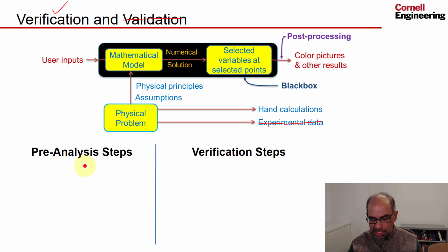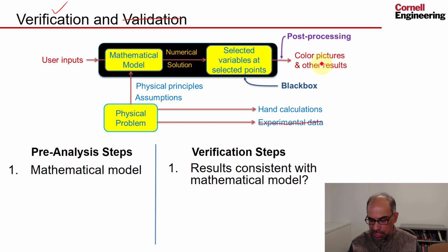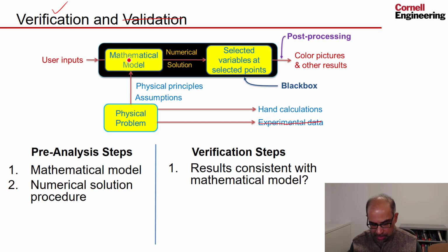And verification builds nicely on the pre-analysis steps. Each step of pre-analysis has a corresponding verification step. We looked at what the mathematical model was, and so in verification, we can check if our results are consistent with that mathematical model. We looked at what the numerical solution procedure and the associated numerical errors are.